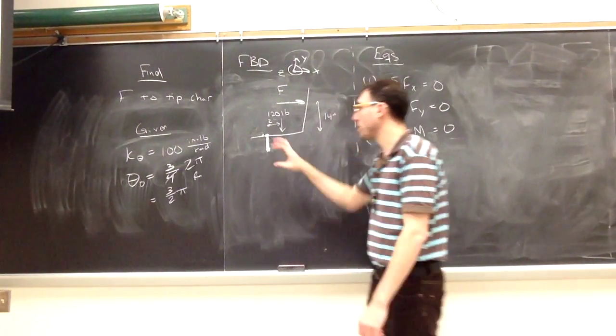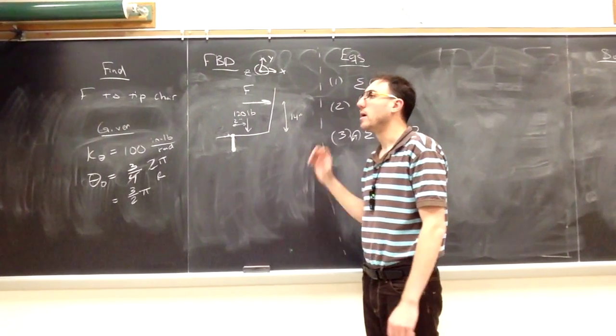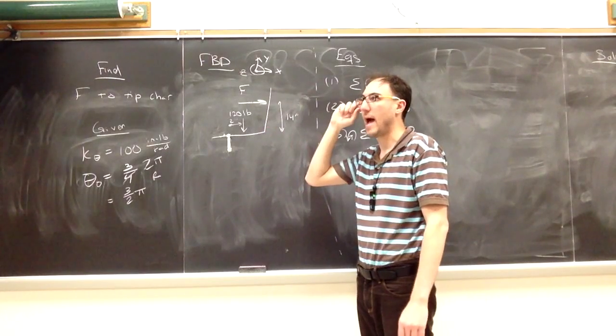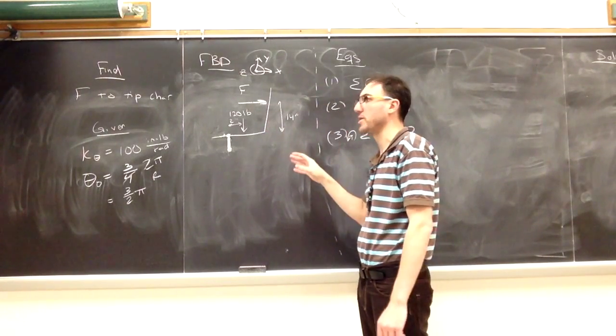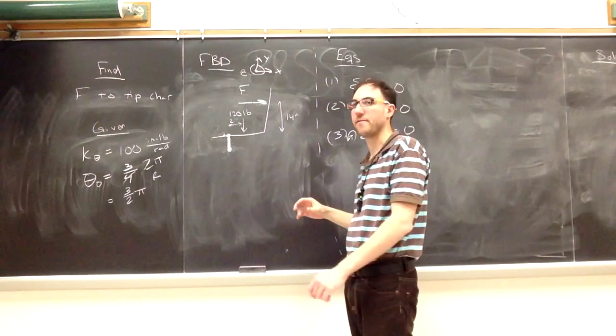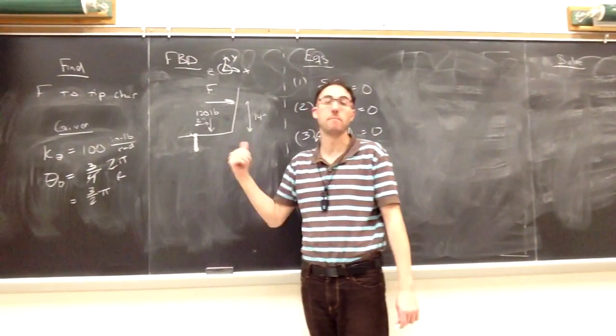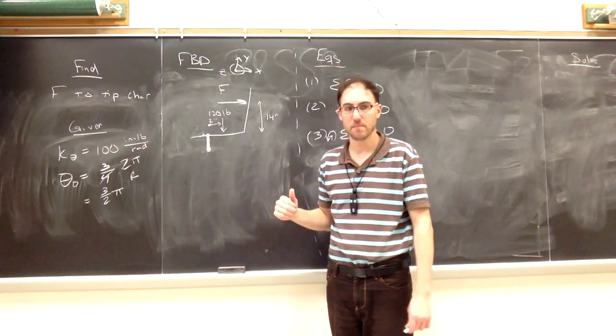What direction should that moment be facing that the spring is imparting on the chair? Thinking about how we normally want the chair to behave, why should the spring moment be counterclockwise? It should still prevent the chair from falling back.